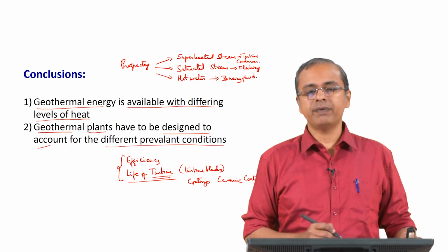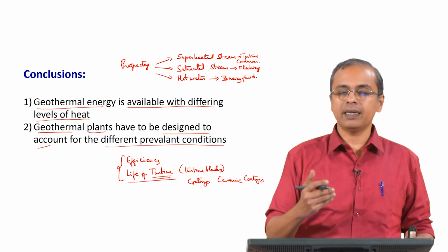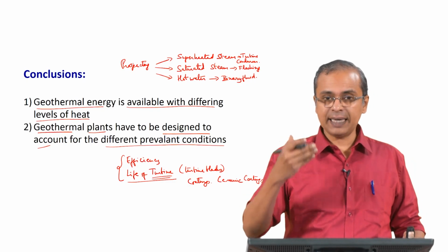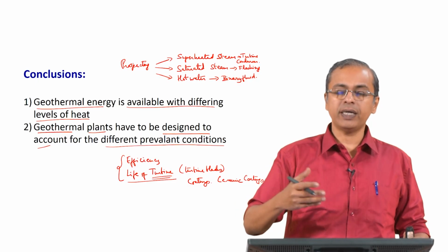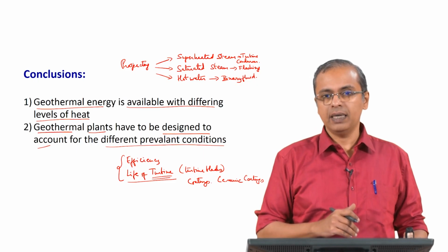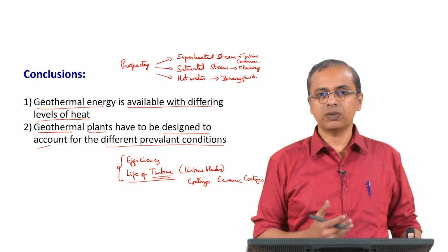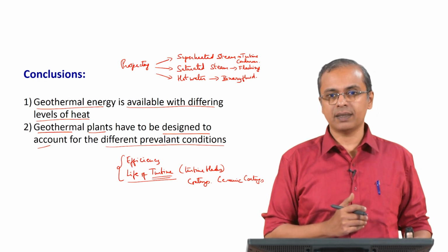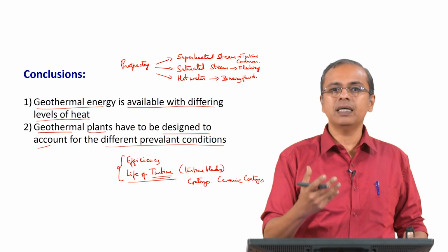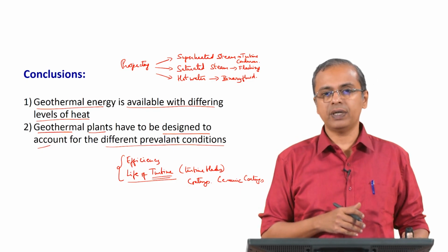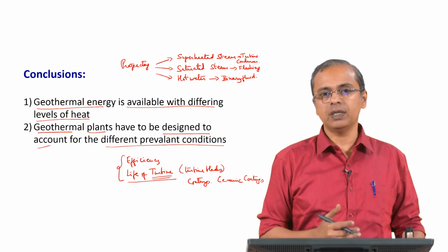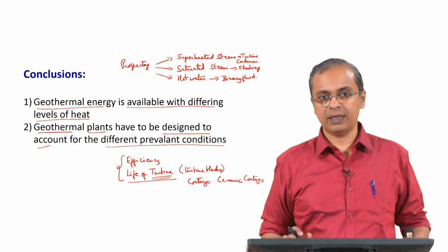So ceramic coatings are often given for turbine blades, primarily to ensure that the turbine blade does not directly get impacted by what is hitting it. And that dramatically increases the life of the turbine blade. Sometimes zirconia-based coatings are used, and they create what are called thermal barrier coatings, which help handle the temperature. Plus, the fact that it is a ceramic coating usually means it is much more resistant to attack from corrosion and so on, and so those coatings are very significant.